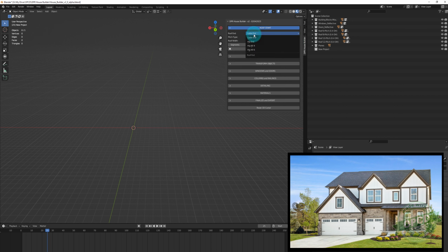So we're going to start with this gable end. That block is 6 meters moving left to right, so that roof width is going to be 6 meters. The segments is how long it is back to front in this image. This is just going to stick out of this structure, so we probably just need 2 segments. We can always come back and fix it if we realize that's a mistake, but usually 6 meters is going to be enough to get it into this larger structure. So go ahead and just click Add Block.